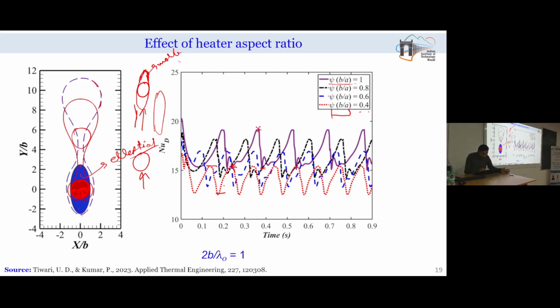However, if you see the overall period of bubble formation and its rise, that is almost 1.5 times that of the period for the cylinder shape. So, though we will be getting a lesser heat transfer coefficient, the number of bubbles forming at this surface will be more in comparison to the number of bubbles formed on a cylindrical surface.